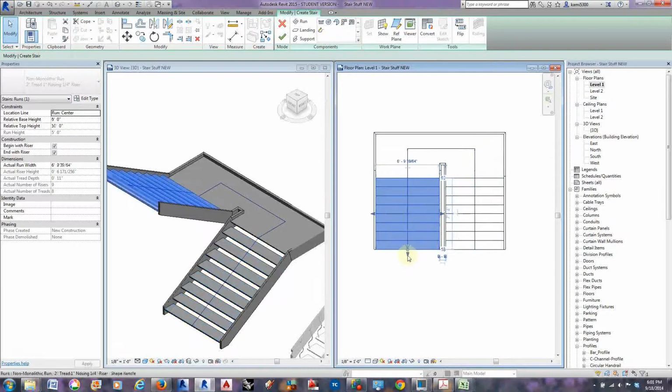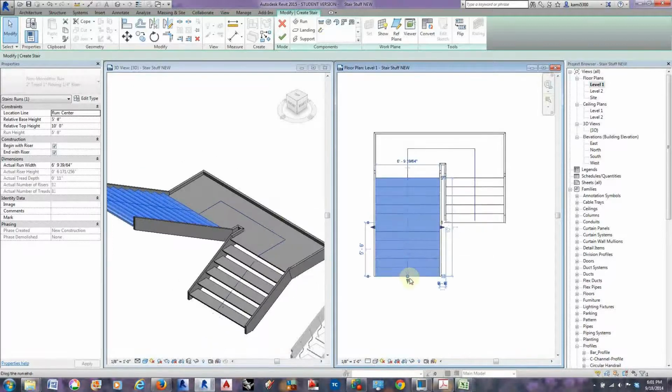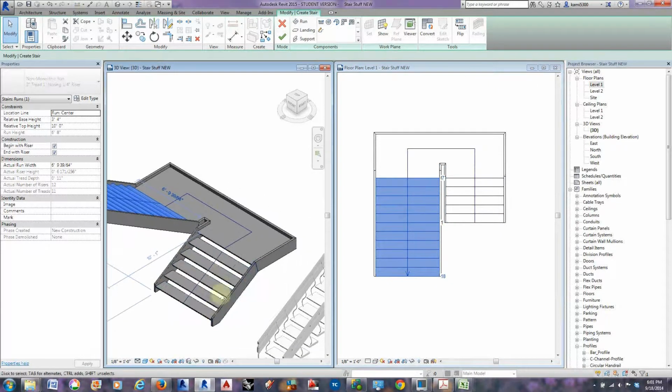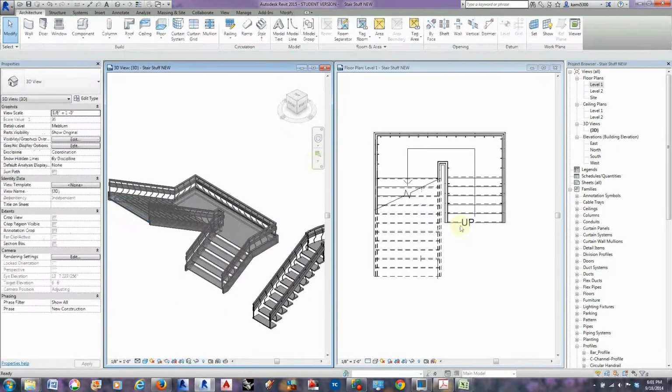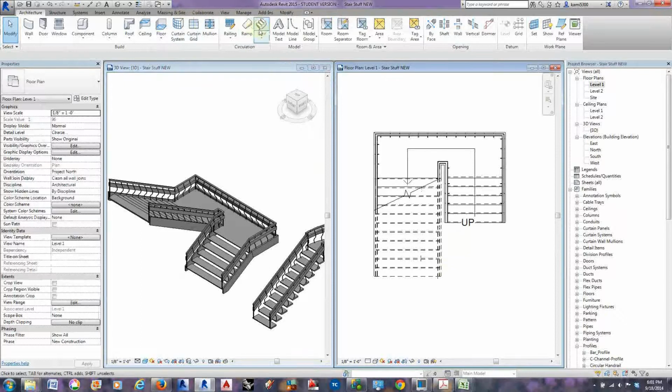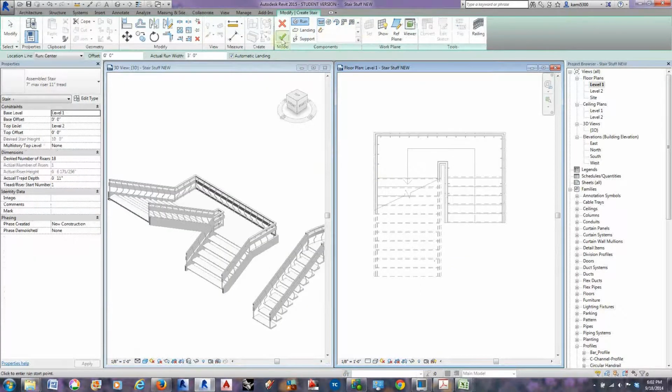The other thing to be aware of is you can change after the fact. So maybe you want 4 or 5 risers here before you hit your landing. You can start to change that, and it shrinks the other side. And so it also automatically adjusts the height of this, so this stays at ground level, and your landing then starts to shrink as well with it. It starts to get lower. I guess it'd be nice to have a floor there so you can see that reference. I clicked on stair.